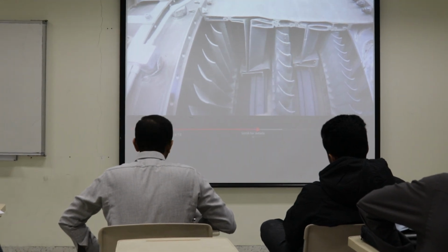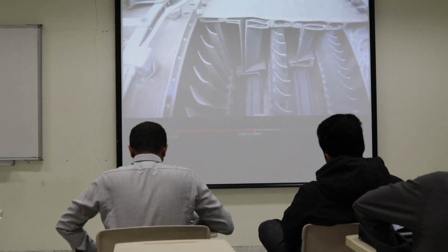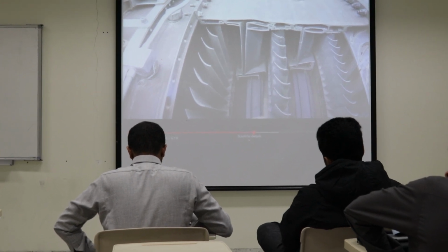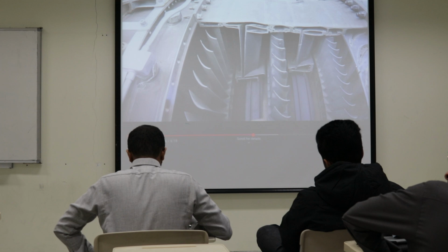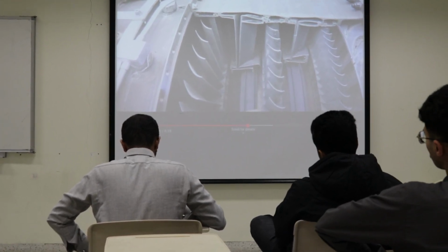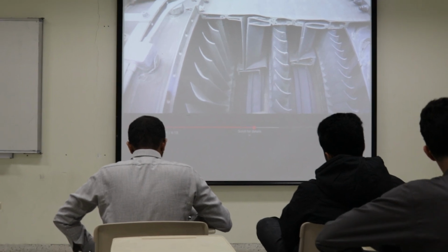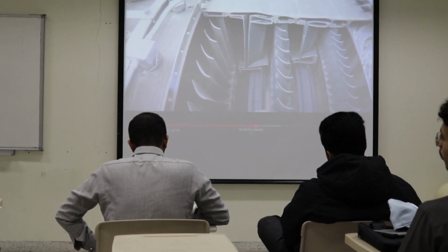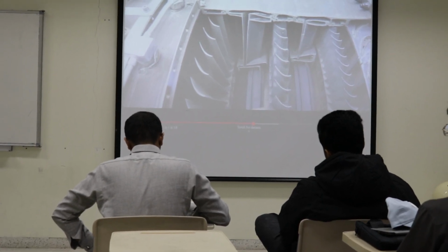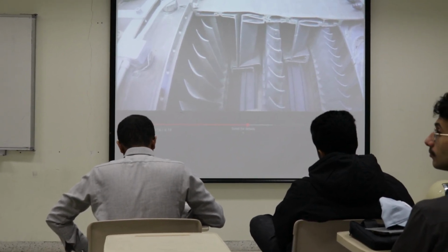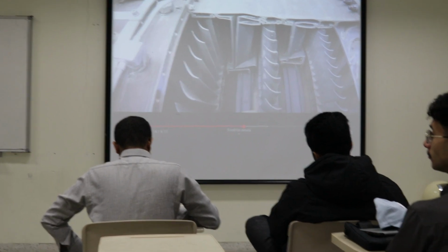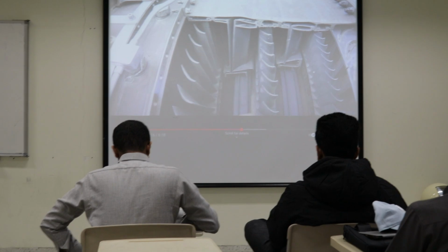You can see the blade is thicker, and we should have cooling inside the blade, at the blade base itself. We have to apply cooling in this case because the turbine is working under high temperature, but the compressor is working at low temperature, so I don't need higher thickness. Also here, the flow hits from the fixed blade to the moving blade. It has to be able to sustain this, and it is connected to the shaft to rotate the shaft.